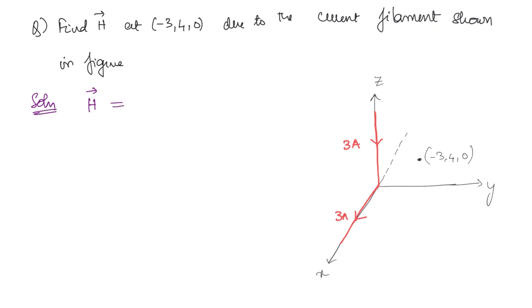So what is that? It is given by I by 4 pi r (cos alpha 2 minus cos alpha 1). And what about the direction? Direction is going to be a phi bar or minus a phi bar depending on the current direction.